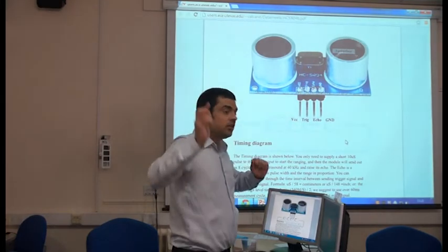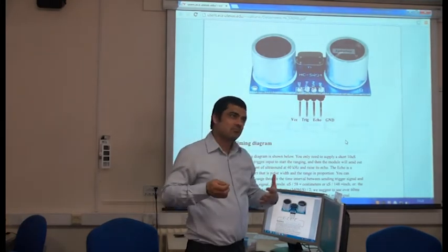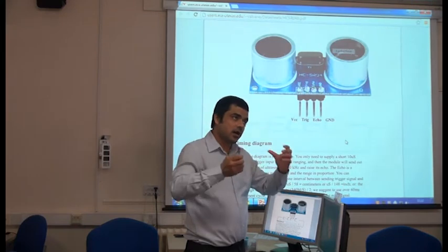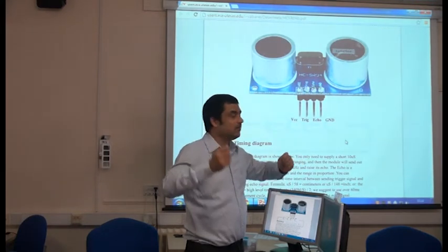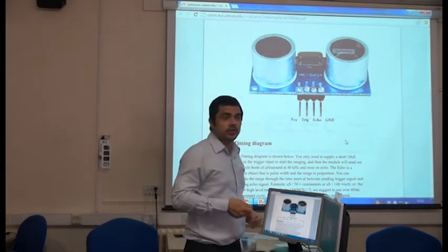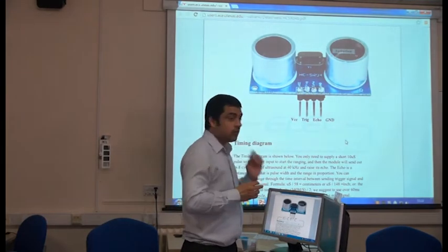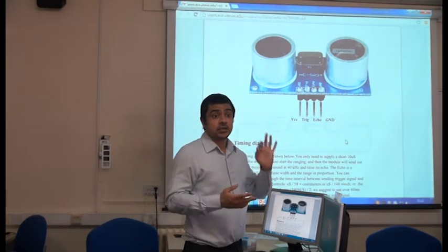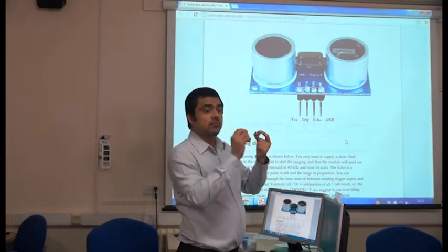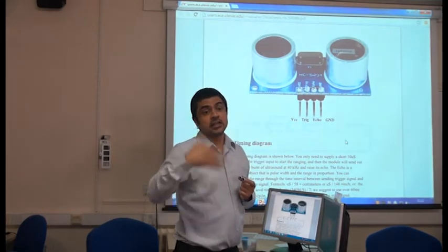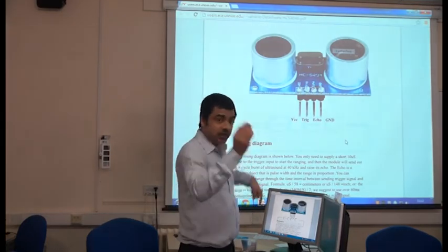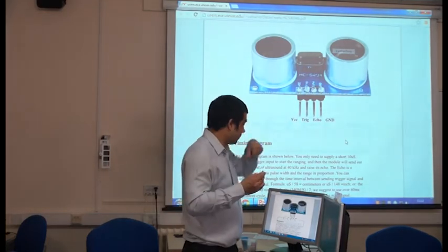And effectively in the 3 pins one, a single pin does the work of the 2 middle pins, which is trigger and echo. If you have got 3, then you need to open the data sheet of your own sensor. So read the name, go to Google, type it, and then you will get a data sheet.